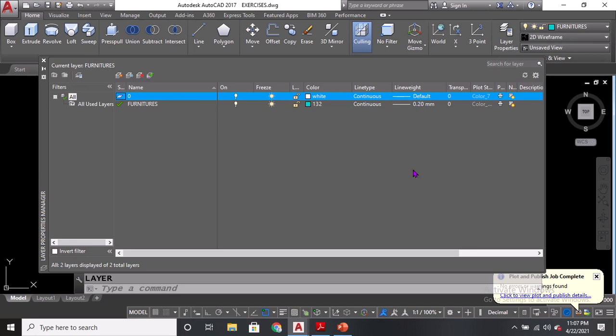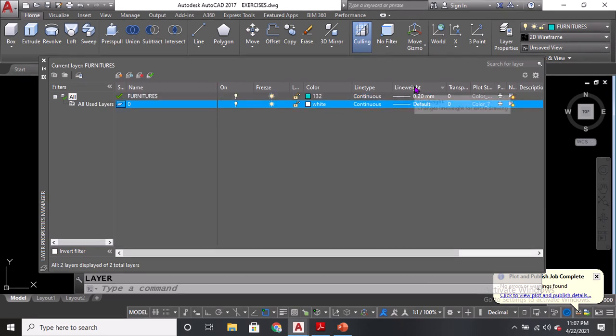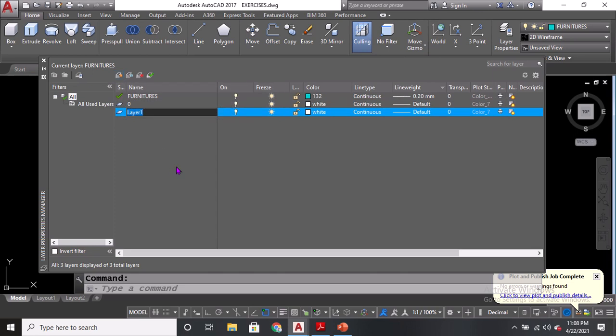So we're going to set three new layers for this. For the meantime, we will be using the layers basically for line weight, because not all objects in AutoCAD should be uniform in line weight. We use line weight basically for emphasis, and then among many other properties of layers is the line type. But we will just be focusing muna on how to set new layers and how to set their individual line weight. Okay, so we're going to add one. The first one is hatch.